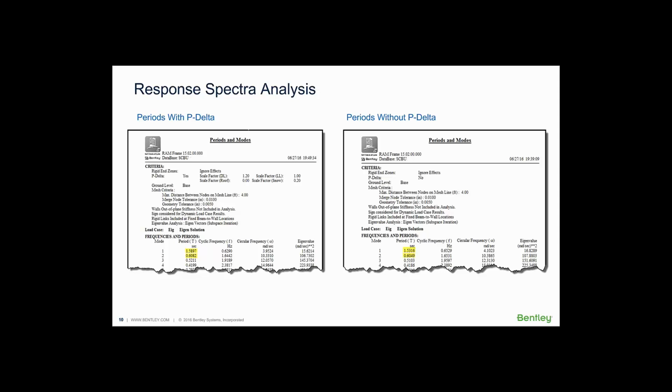And then somebody also referred to my B2 factor of 1.08. That was just for this building. So you need to run the analysis. You need to go through either the AISC Appendix 7 or 8 indicates how to calculate the B2 factor, and the ACI specification indicates how to do the moment magnifier. You need to go through and perform that for your structure, and keep in mind that that number is potentially going to change at every story. And so you need to go through a calculation.